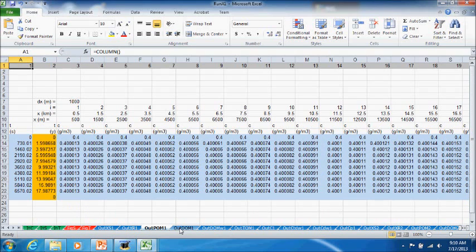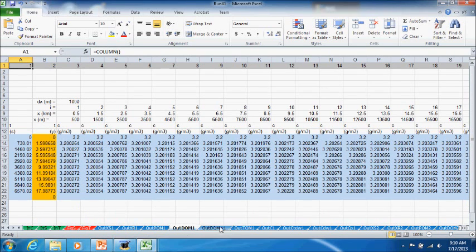Particulate organic matter, dissolved organic matter, dissolved organic matter in the water column, and you'll see there's a difference here. These are both in the water column, DOM1 and DOMW1, but W1 is on a volume water basis. Okay, so you can quantify the concentration on a volume total or volume water basis. For the water column, they're going to be the same, but for the sediment bed, because there's porosity and pore water is only a fraction of the total volume, those are going to be different.